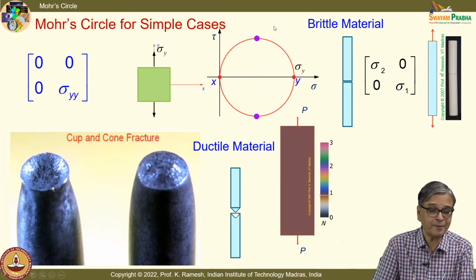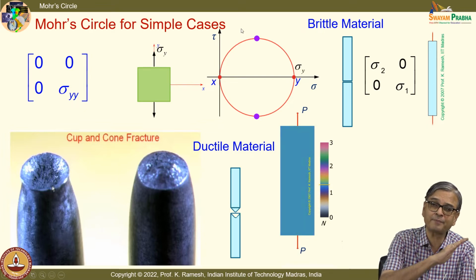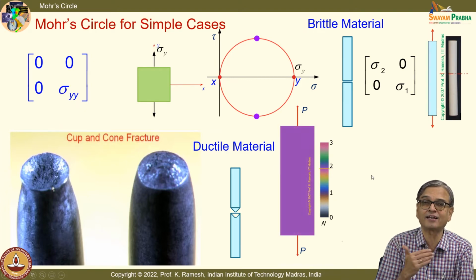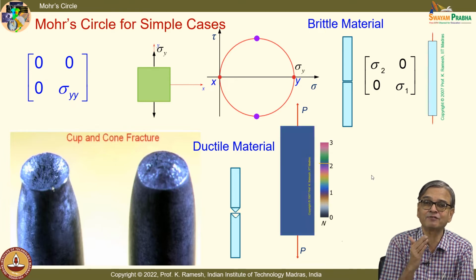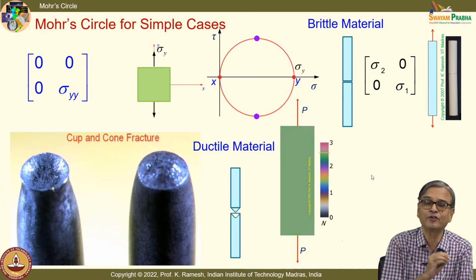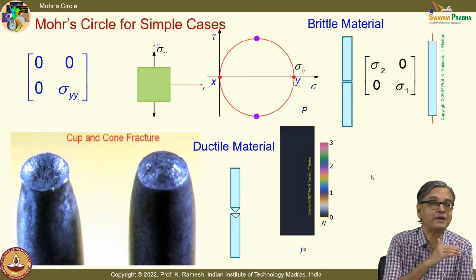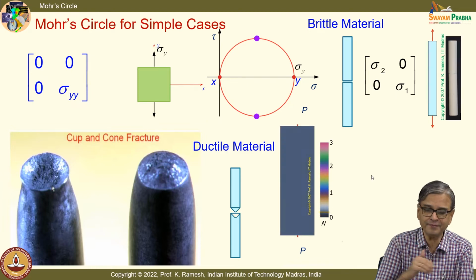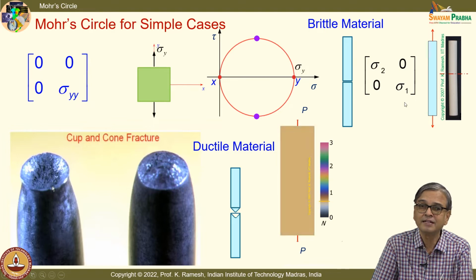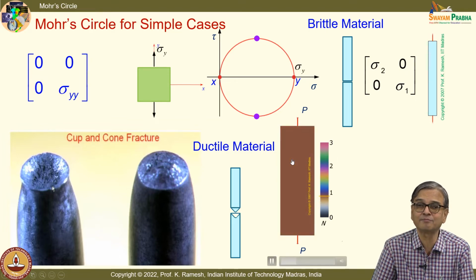This is a graphical representation of what happens at a point of interest on all the possible infinite planes. This is again a graphical representation. Fortunately, the experiment is so colorful, you get colorful fringes. And then we have seen at every point it has a constant color for a given load. So, you understand that the complete material participates in load sharing, and the only non-zero quantity is sigma 1, and you can say that this is related to sigma 1.